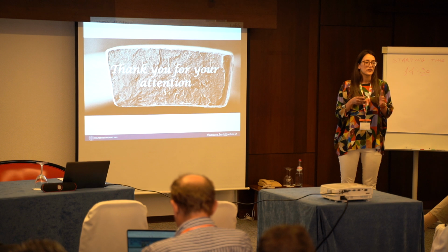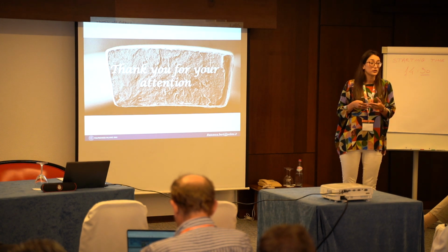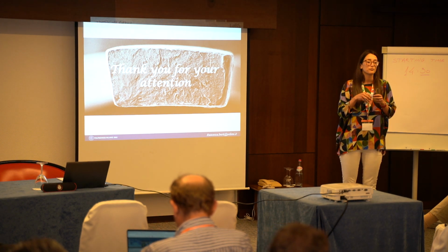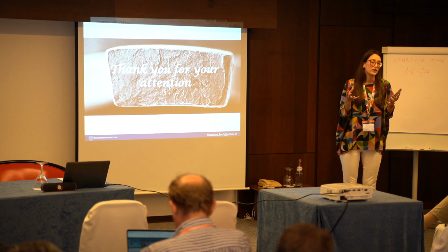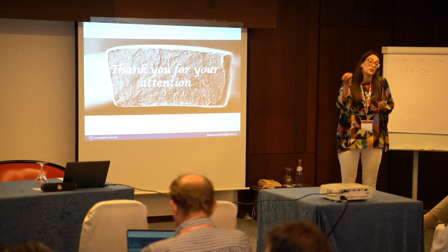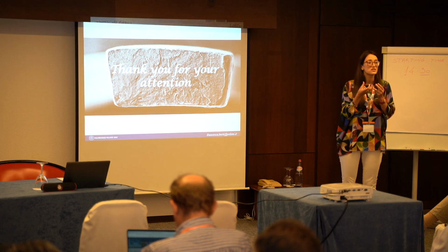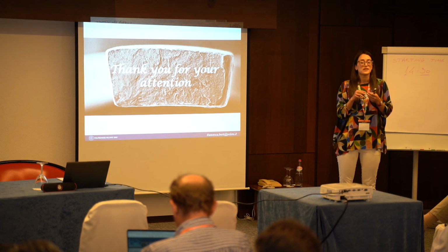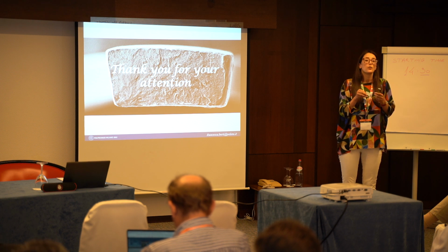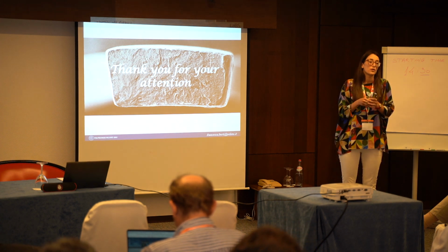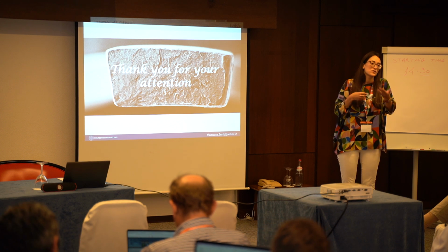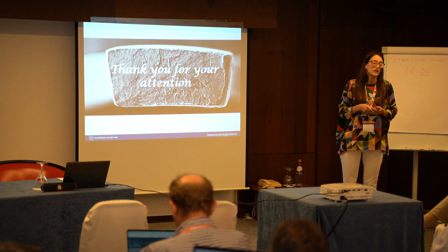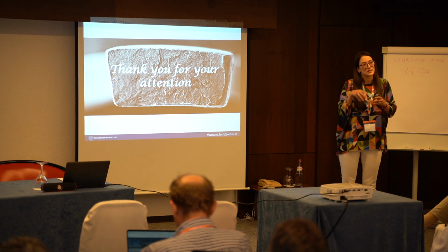Obviously in a stent it is an assumption, because we have to decide if we consider the macroscopic R ratio from the applied load, but we know that in a stent the complex load makes a different story at the local level, so we need to evaluate what is going on. So this is an assumption based on what is happening at the local scale of these stents.